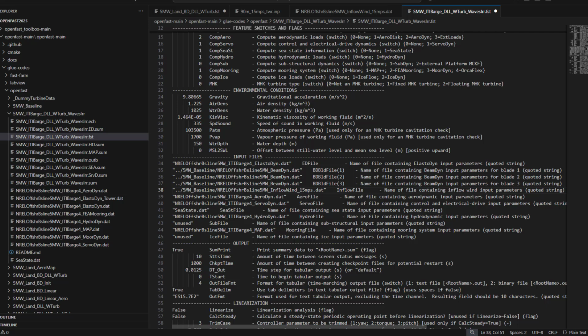So whatever the case, the location of this file has to correspond with what OpenFAST has done in generating this program. So if this file is placed in a different folder, either you change the whole of this file name or you relocate this file to the folder that the OpenFAST runtime is pointing to in order to avoid any errors.